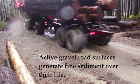If you are actively logging a site, you will have no doubt experienced traveling behind a logging truck on a wet day that is spewing up large amount of mud from the road. And meanwhile, lots of pickup trucks have gone by and you haven't seen the mud, but you are seeing it now with a logging truck. The heavy loads result in extreme forces on the roadbed, and hydraulic pumping results that brings fines to the surface, and then those fines will be open to erosion. The more activity there is on a road, the more fine sediment will be generated. The amount of heavy traffic is an important criteria for determining how much sediment will be generated on a given road.